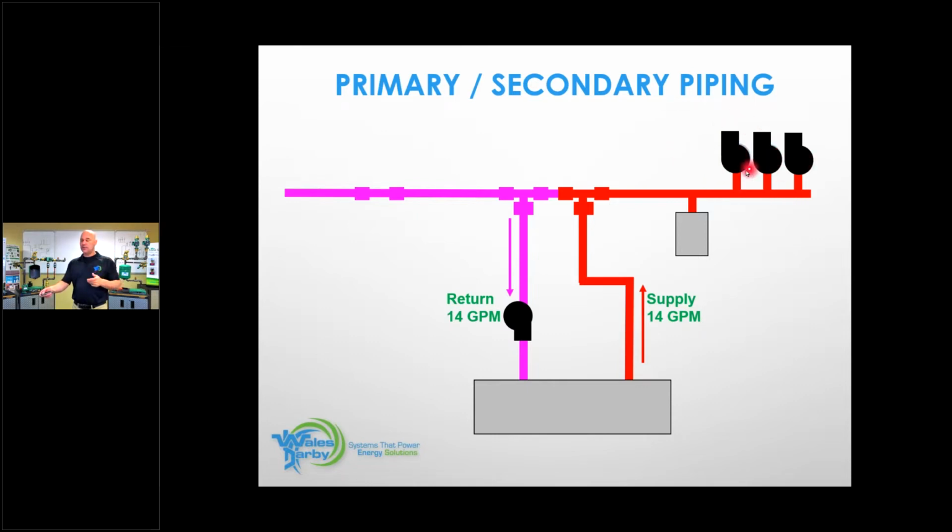Okay? What I would like to see, if I'm paying for the gas in this system, I want 0 flow between those 2 closest spaced T's on a design day. And why would I say that? I'm paying for the gas going into that boiler. I'm producing BTU with that gas. I want every BTU on the coldest day of the year to be delivered to my home. I don't want any bypass going on between the 2 closest spaced T's, whether it's reverse or bypass forward, because that's going to change my delivery temperature on the coldest day of the year, the delivery temperature of that water to my baseboard.